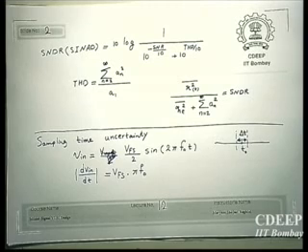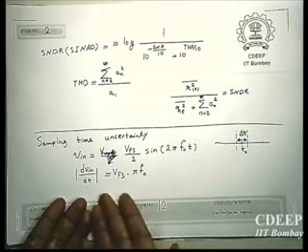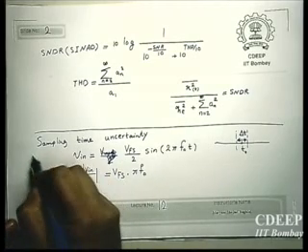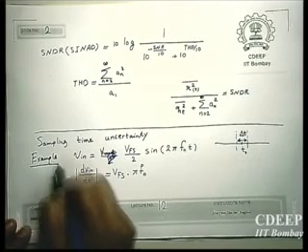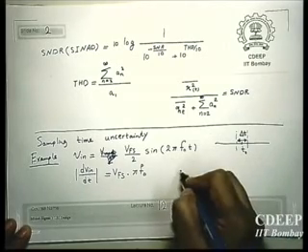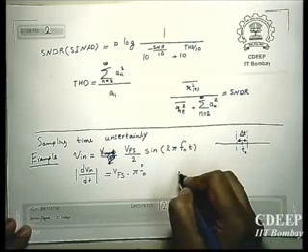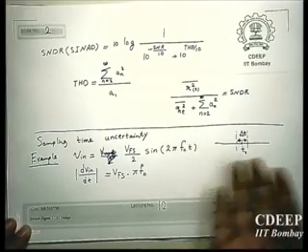Of course, smaller is better. So now what will happen? We have a maximum rate for the input signal, this is just an example, and you have some uncertainty, which we call delta t, for a given sample and hold, specifically the sample and hold. So during this delta t, how much may your Vin change?